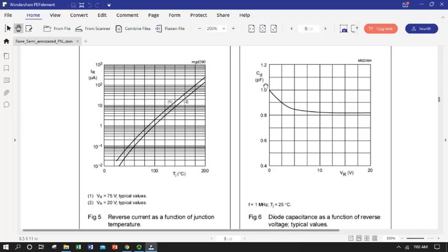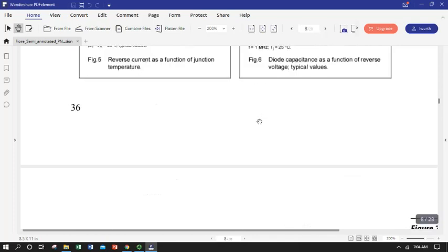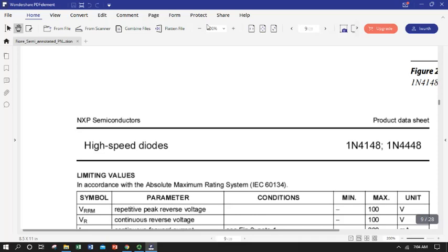This is a plot showing how that PN junction interface acts like a capacitor, because it does. So as we apply more and more reverse bias voltage up to 20 volts, the capacitance created by that interface drops because we're increasing its width. And we can actually take advantage of this in particular diodes called varicaps, where we have a diode that we deliberately caused to act this way in a predicted manner, and so it acts as a variable capacitor. So that's just taking advantage of one characteristic of our p-n junction.